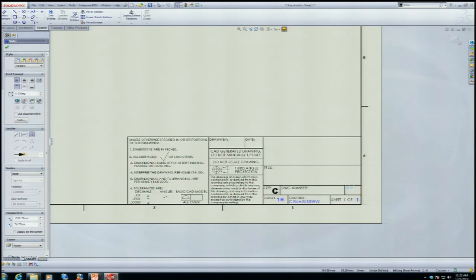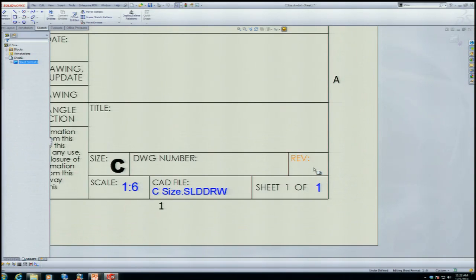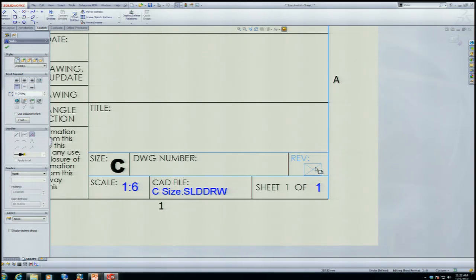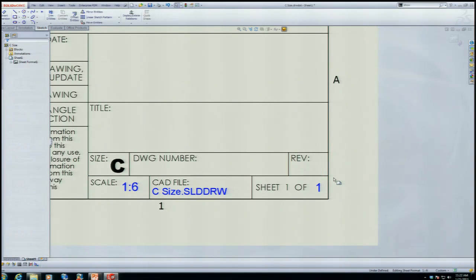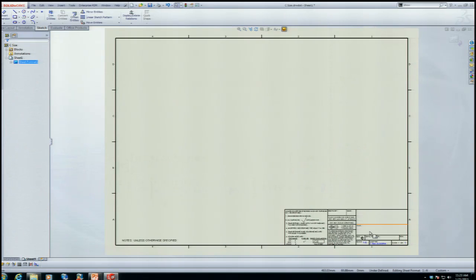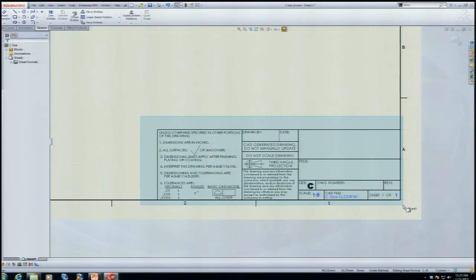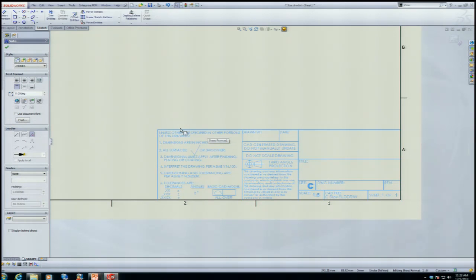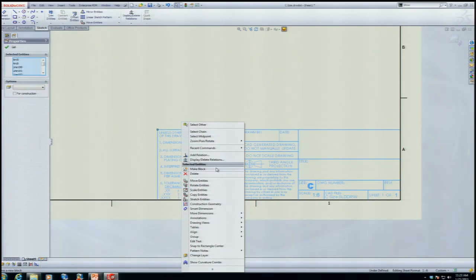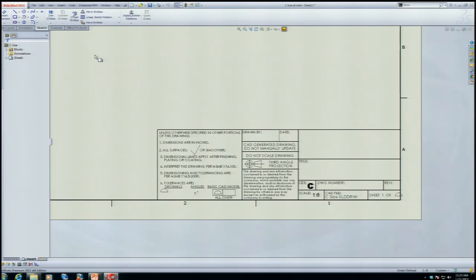And I'm going to delete. I see there's an extra. See how that works? The difference is now I can isolate that one item there and delete it. So I'm going to highlight the entire title block, right-click on it, and make block. Select my insertion point. It's good to do this with the title block and border already in place because then I can just take the insertion point and drop it right on that corner. That makes your life a whole lot easier later on. Do you know what the 2 components are to that, the insertion?